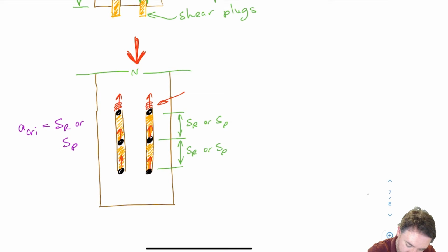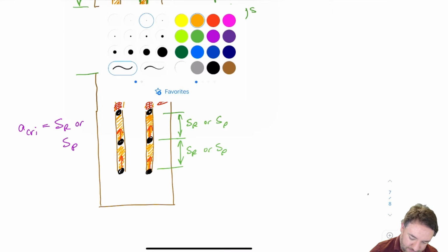So what we're assuming in that direction is that we have a plug over here that is the same length as the row spacing, that it fails as well into that piece of wood. But really it's embedment failure that's happening at that. So when we're talking about row shear failure in compression, it's an approximate approach, but we're supposed to check it anyway, using the same equation basically.